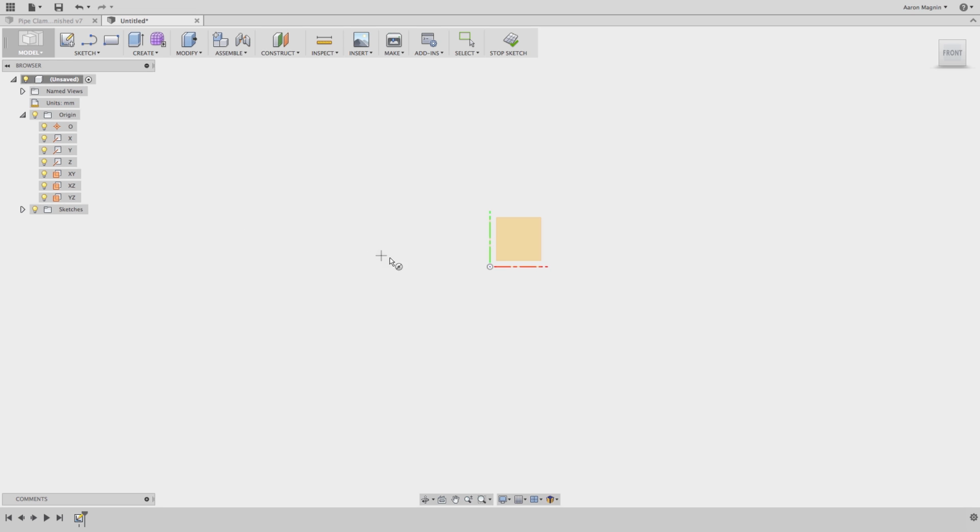So at this point, I'm going to move my cursor over this center point, this origin, click once, and I can key in a value here. Right now it's in millimeters, and that's really not how I want to be designing this, but it doesn't matter. We do have some nice options here to work past this. So I'm going to say 2 and type in IN. It's going to actually convert that into an inch dimension.